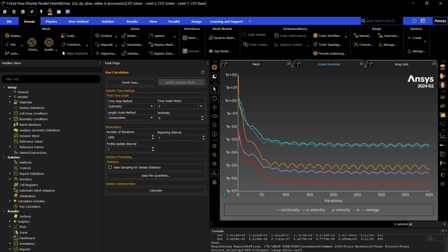So that's done. Now this could mean either one, it's just turbulent, it's just normal or natural, or two, it could be the mesh. We can check the mesh right now. Now we're using K omega, and with K omega, and probably K epsilon as well, not too sure, but I know for sure that with K omega, you need your wall y plus, which is a turbulence parameter, to be under 1. It has to be below 1, okay?